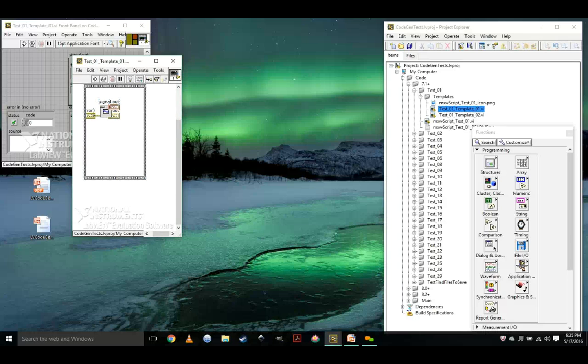So what I've done here is I've got an error. This is actually not going to be deleted because that will be connected eventually. These 2 terminals are going to be connected to something on the other side. So they're just stubs, and they will be deleted before the code is finished. The alignment of those and the reason they're so shoved into the actual sub-VI is so that it doesn't take up any space. I'm trying to contract the space of the actual terminal. In fact, the connection point is going to be in the center of the terminal, and it knows it's the center of the terminal. It knows not to use the text. Your templates are going to be kind of squashed for that reason. Yeah, they can look squashed.